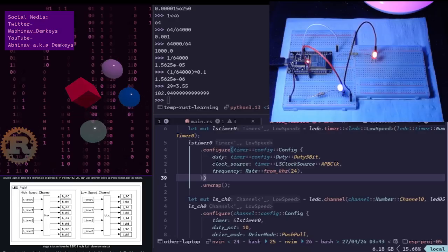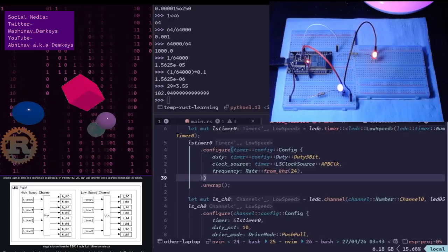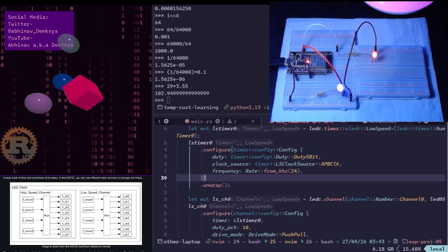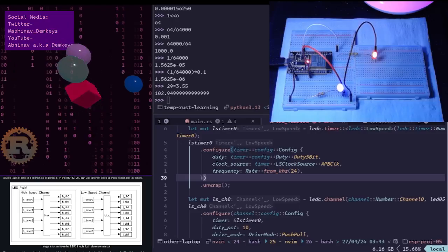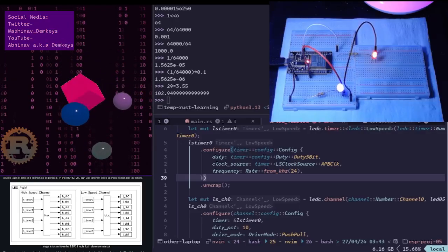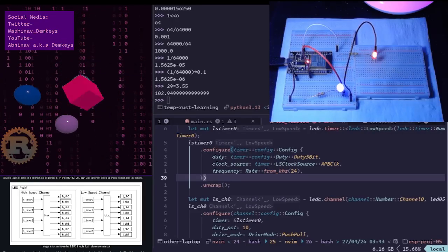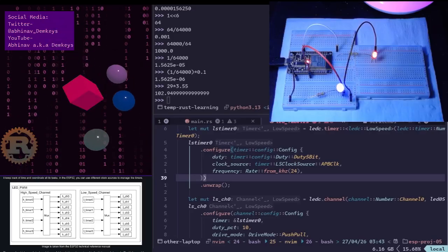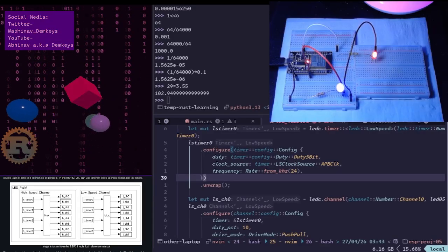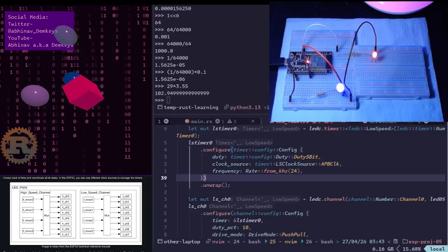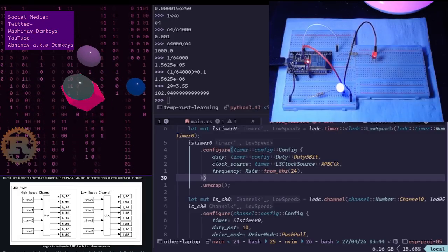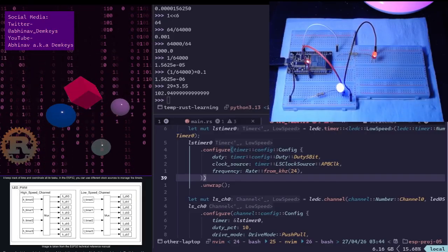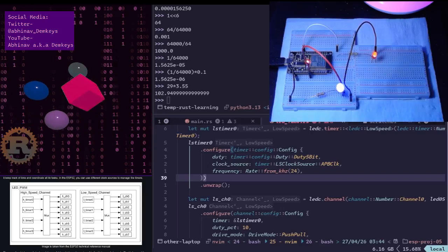something changes. Why doesn't the memory vanish when the CPU sleeps? This is the key. The ESP32 is divided into different power domains. The core domain contains the high-speed CPUs. This can be completely powered down to save energy, and then the peripheral/RTC domain contains the registers for things like PWM, timers, and the ULP.